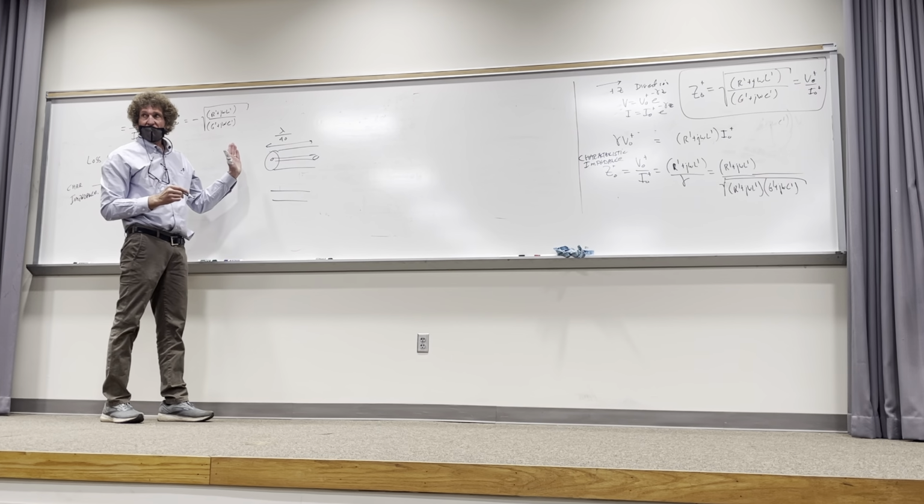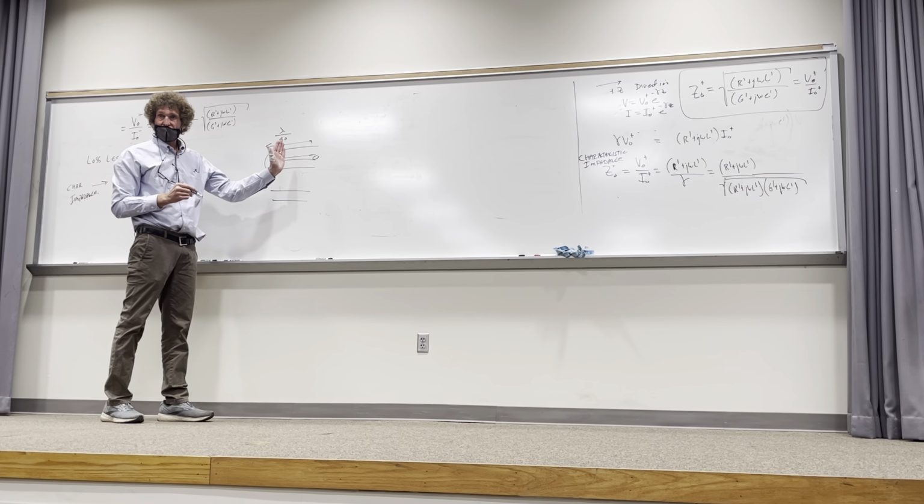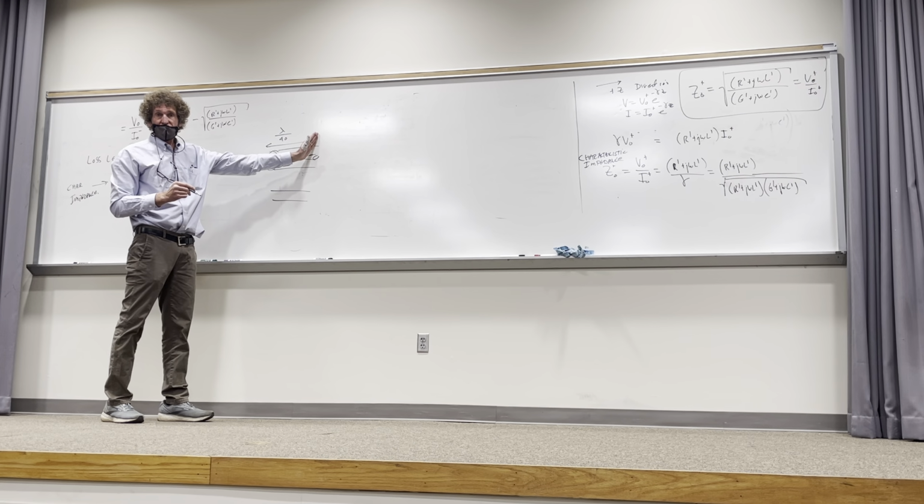The cable will behave as having a characteristic impedance of 75 ohms when the length of this line segment becomes a tenth of a wavelength or longer. It's not abrupt, but after a tenth of a wavelength, the ratio of voltage to current is closer and closer to the actual characteristic impedance. Do y'all hear me on that? Just listen to me, because here's what people do.